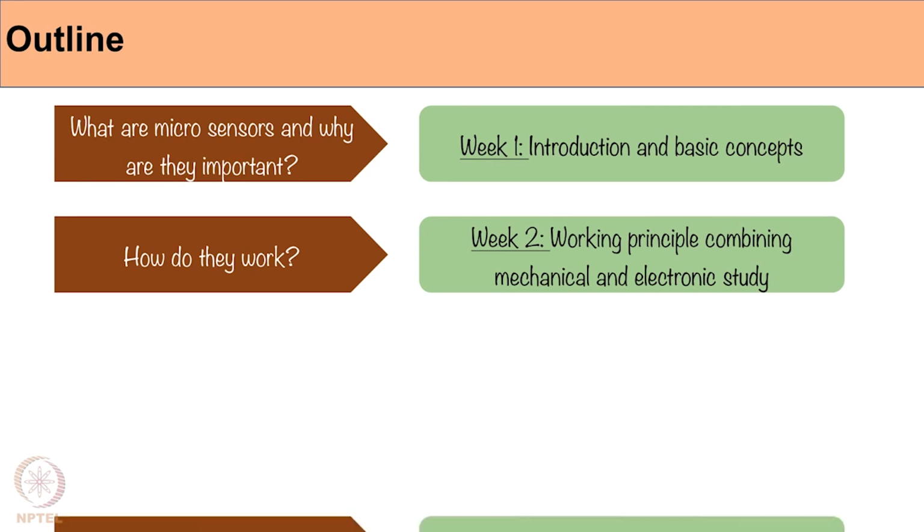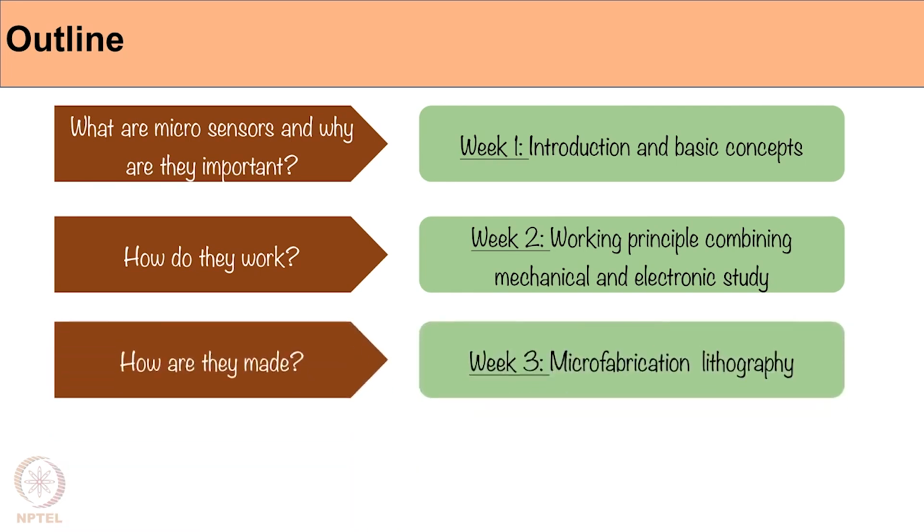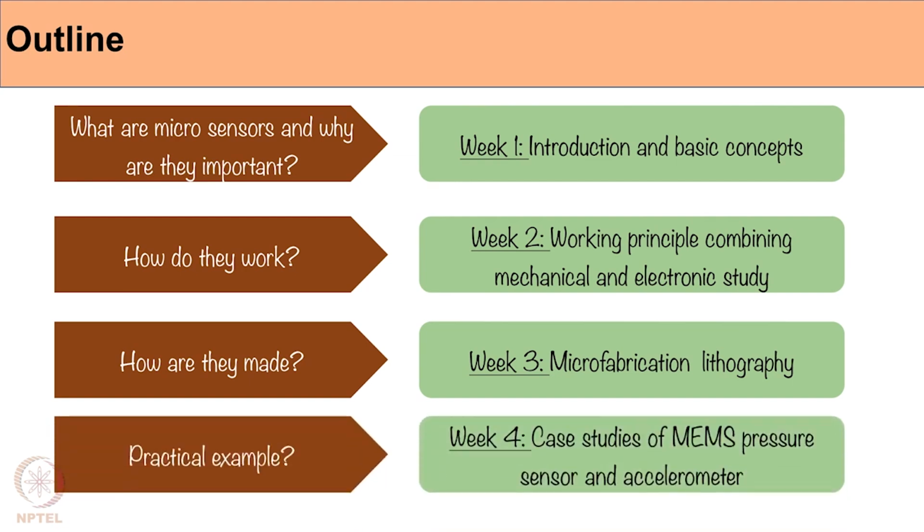Next is the most important part, how they are made: microfabrication or lithography, the usual techniques for making these devices. Finally, practical case studies with specific examples of a MEMS pressure sensor and an accelerometer, and we will use this knowledge to make these two devices.